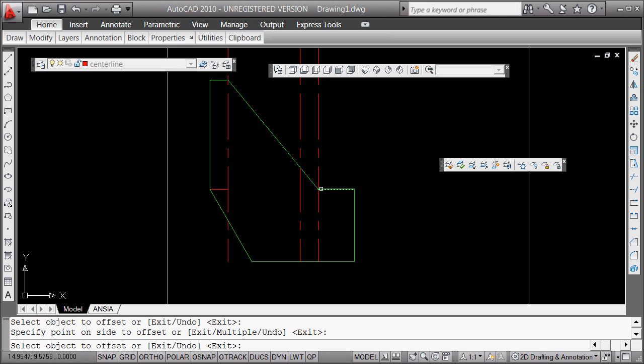You will see in all reality, it's important to realize, if you're doing mechanical drafting, the dimensions hold, but you do want to use the visual clues. So I'm going to draft this the way it's shown, as 0.5 over, and then I'm going to draft down 3 and 4 with these offset lines. So I'm going to say offset, typing an O this time, spacebar, 3, that takes me there, and over.